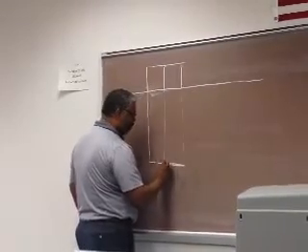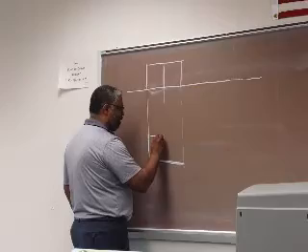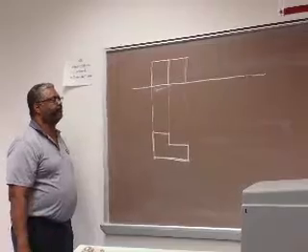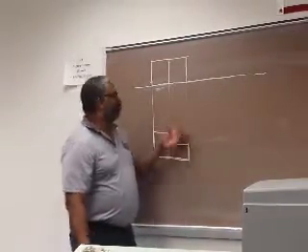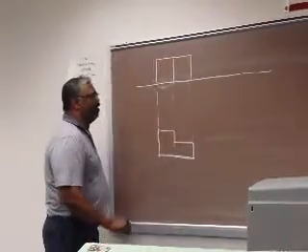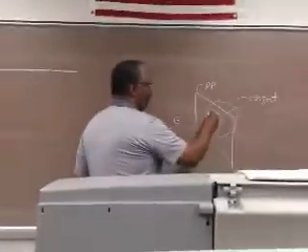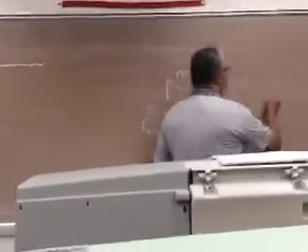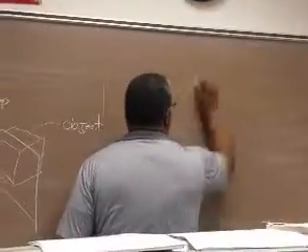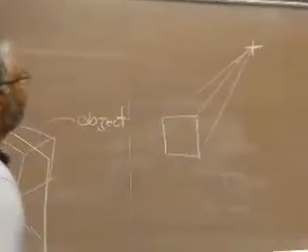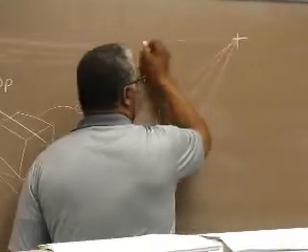So this is the true, on that plane, this is the true size, and we're just going to have an offset like that. That's the true size of that front view. That gives you a reference for your other distances. Now, the further the object gets away from you, the smaller it appears. So when I look at the front view of an object, the further it gets away, the smaller it appears. And with a perspective, it vanishes at a point, and this point sits on the horizon.